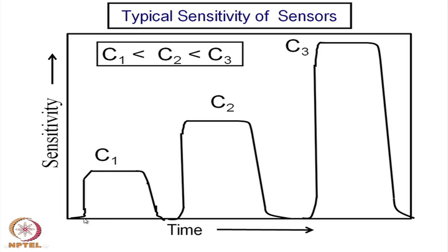And this is your kind of response time. Okay. This is the time scale. At this time it can be a 0 time here. How much time does it take to go to the saturation? That from this point to this point is your response time, and you can see the recovery when this particular gas concentration is withdrawn. It is coming back to 0, but at a slower pace. Okay. So, this recovery time is slightly larger.